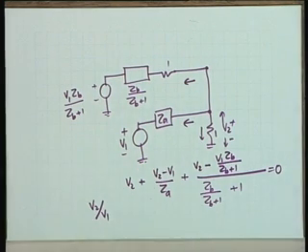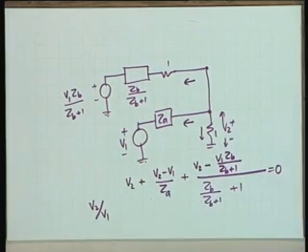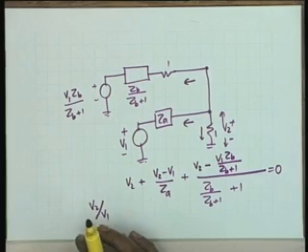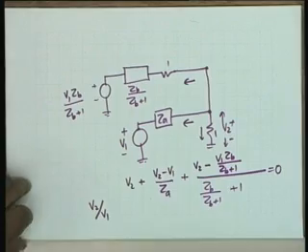Any question? These are some of the tricks that one exercises. You will not get this in a textbook, but it's common sense. I have also cautioned you that had the input been a current source, the procedure would not have been valid. Have I or have I not? Current source cannot be split like this. Number 2, if this voltage source had a non-zero internal impedance, then also we couldn't do this. It's only in the case of an ideal voltage source that you can split, not otherwise. Okay, part B.